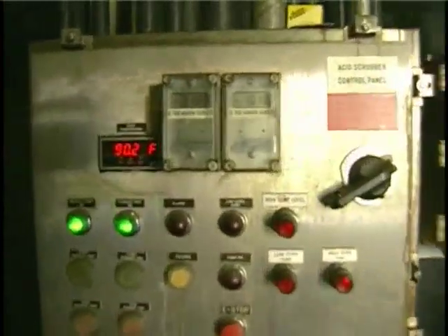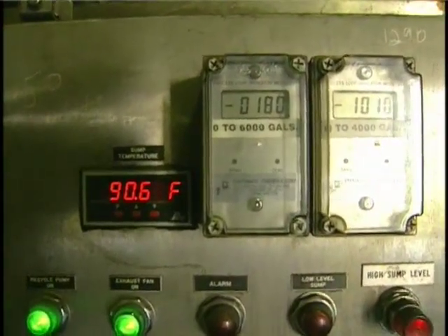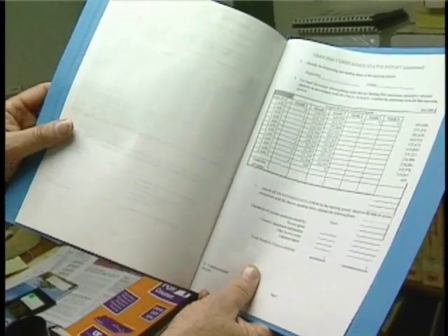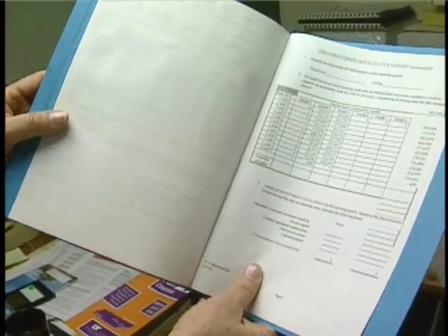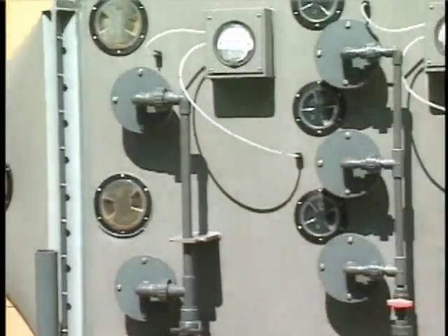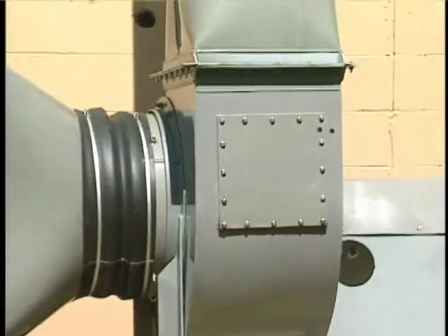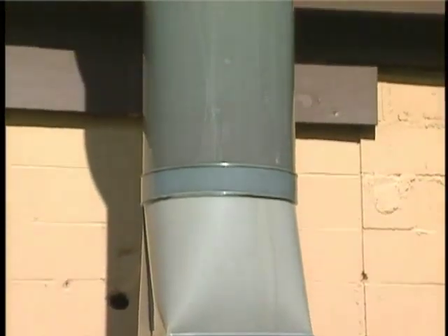The liquid flow rate into the scrubber is also important. If the flow rate is being monitored, the value during the inspection should be compared to the baseline or permit value. A decrease in the liquid flow rate without a proportional decrease in the gas flow rate will usually cause a decrease in the collection efficiency.